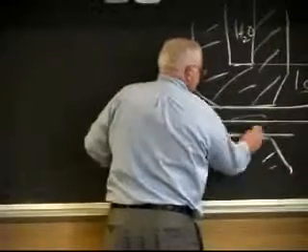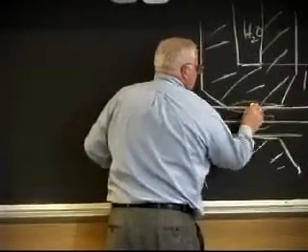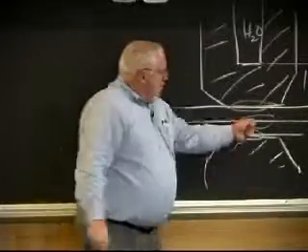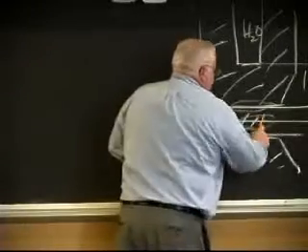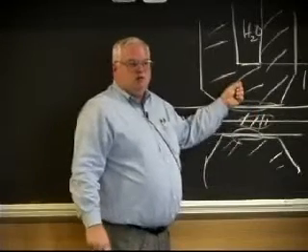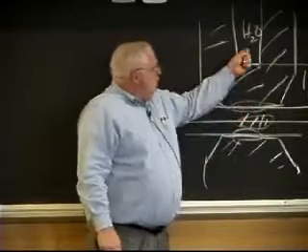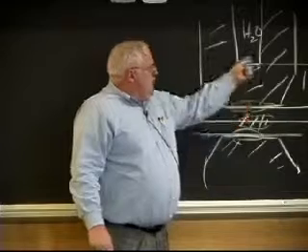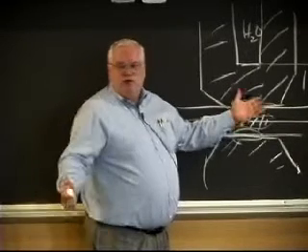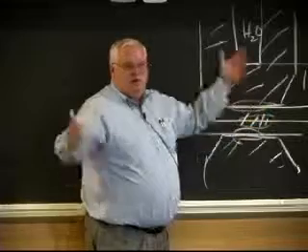You saw some videos that show heat generated from resistance at these interfaces. So I want to generate heat here. I don't want to generate it here because I don't want to wear out my electrodes. So will that water be effective at cooling copper 1 centimeter thick in a 1/10 of a second? That's one of your homework problems. I can tell you right now the answer is no.